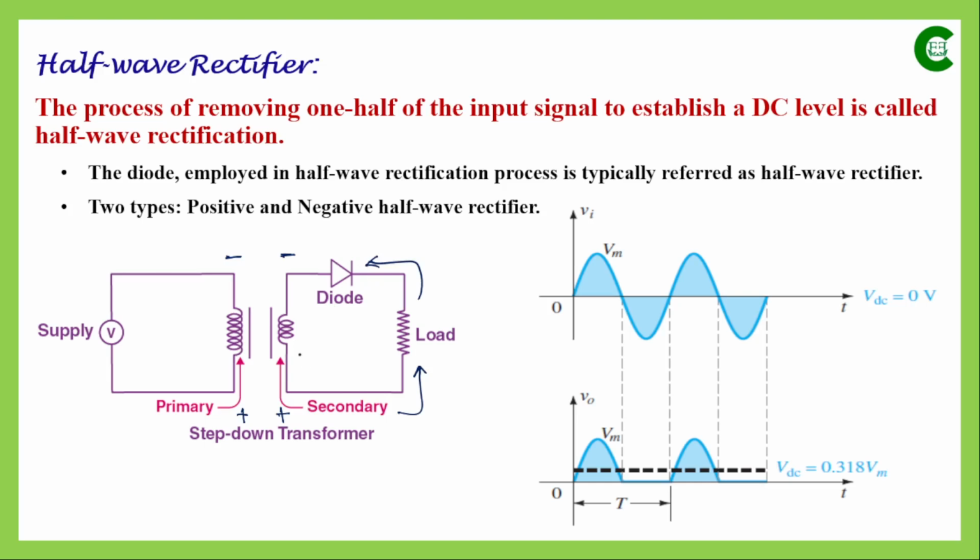And since this rectifier circuit will work as open circuit, no current will be flowing through the load. And since no current will be flowing through the load, the voltage drop, as per Ohm's law, is the current flowing through that particular resistor or load multiplied by the resistance value. So current is 0, that means the voltage drop across the load will be also 0, and that's why in the output waveform also the voltage drop across that load resistor is 0.